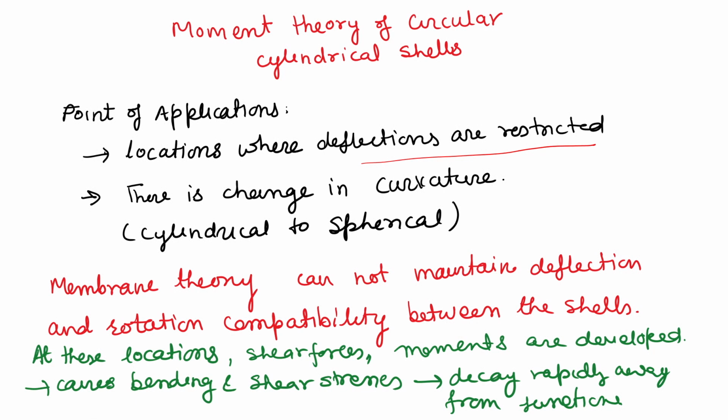In the case of simply supported, we have satisfied only axial stress, we did not satisfy W is equal to 0. If we have to satisfy, let us say, a clamped edge, where my cylinder is clamped at some point, then your deflection is 0 and slope is 0.